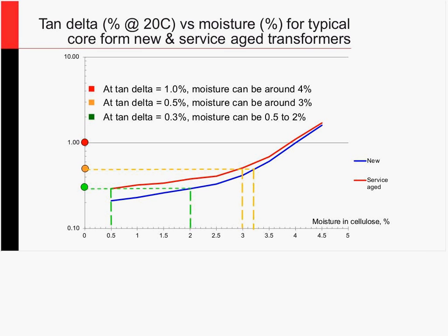with 2% moisture content. Well, just to give you some frame of reference here, if I had a transformer that's testing above, say, 1.7% moisture content, then I'm not liking that so much. I would start targeting that as a candidate for a dry out.